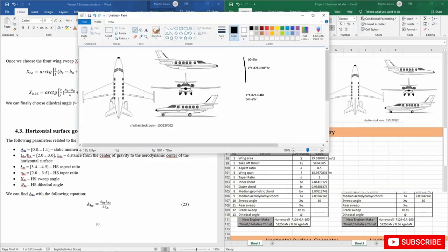So let's say if we would have a crank, our wing is not going to look like this, but it will look something like this. So straight line until here, and then there is an angle here, right? And actually on A320 and A330, they all have this type of crank in order to control the flow distribution on the wing. So the crank is actually this one.